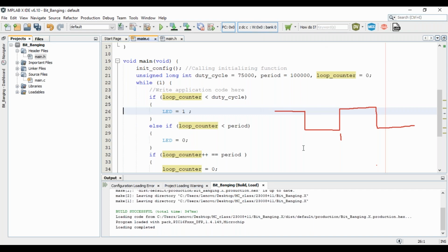So just to show you that lower frequency is important for our operation, I just wanted to show that it is glowing with 50% duty cycle. So which is why I'm showing it like this. I just wanted to show a pulse. I cannot show the pulse as I don't have an oscilloscope. So I'm showing it fed to the LED. So in that case, if you observe 50% of on period, 50% of off period, you have to understand that there is 50% of duty cycle being provided.